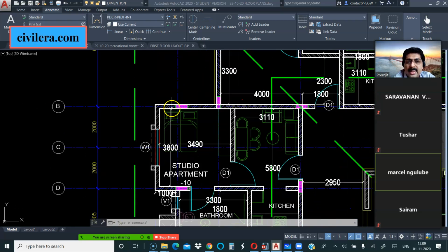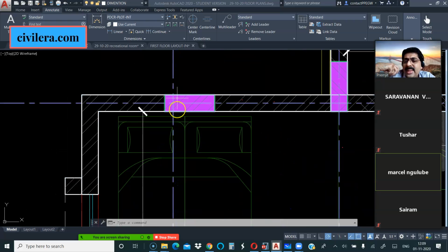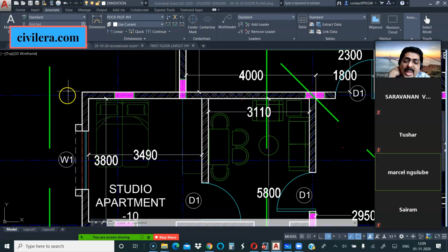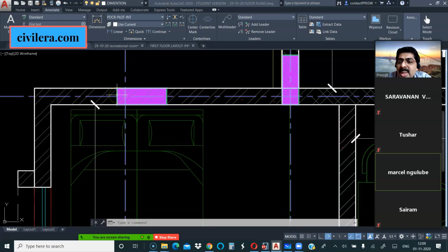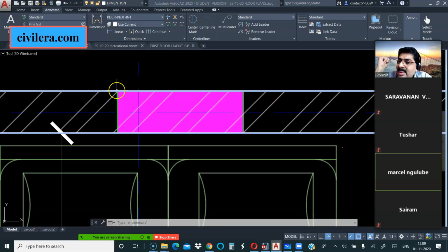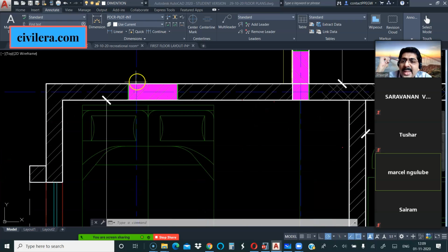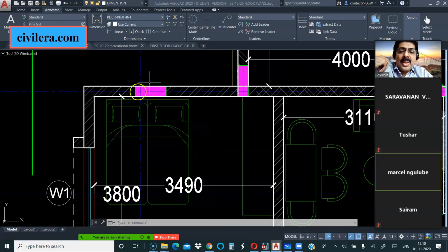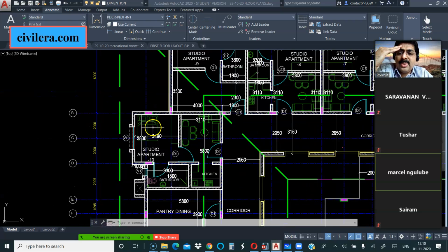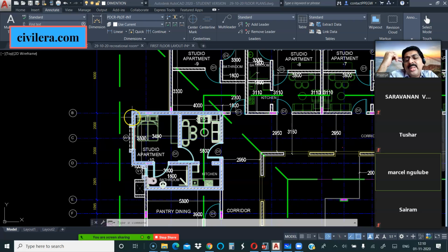No, see the plan. This one, right? Yeah. So see here, I cannot rotate it inside. So here you have an issue. And going to the end was also not feasible because of some regulatory issues, because the setback or something was a concern. So the architect was not okay to have this column at the end. So we had to limit the location here in this particular case. I cannot rotate it inside. It is coming and clashing with the space. So that was the reason. Maybe the steel would have been slightly less if the direction was the other way. Not sure. So there are various things like that, and you have to strike a balance between them.